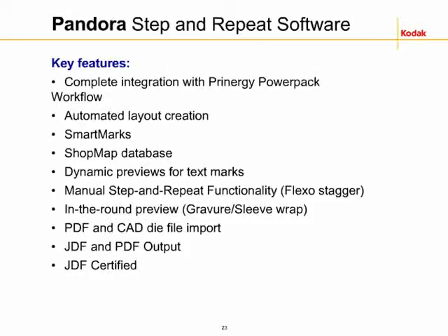The strength of Pandora really is in this versatility, though, in that it can handle virtually any step and repeat configuration and requirement. It also has smart marks, which is a system we've developed that allows you to have special marks on the plate that will adjust based on the conditions of the plate. Meaning that if you change your repeat, if you change your web width, the marks can automatically readjust themselves. You're not having to replace the marks. They're never anchored to any one point statically within the layout. They actually are dynamic, and they move around, they adjust themselves based on the conditions you've determined within the mark system.